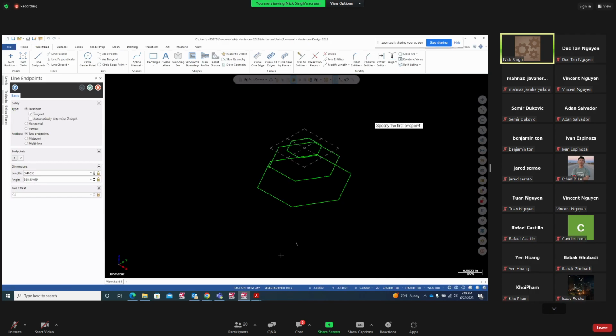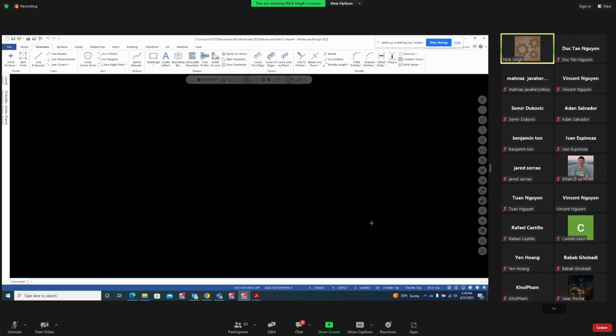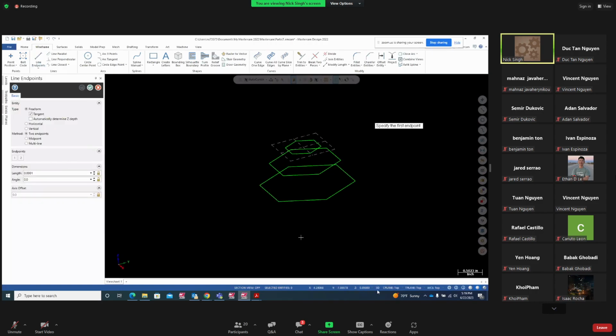So in that case, if I'm going to join this line to this line, we have to go back to 3D. So make sure you click on 3D, guys. That's very important. Click on 3D. Now we are in 3D. So in 3D, I can join a line from any Z to any Z, starting from Z0 going to Z0.5. Look at this, Z half an inch. From Z0 going to Z0.5. From Z0.5, we can go to Z0.850.